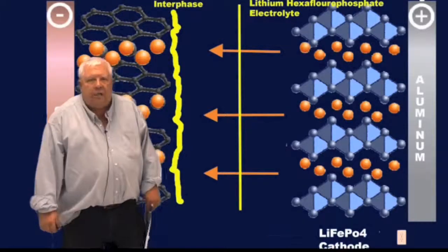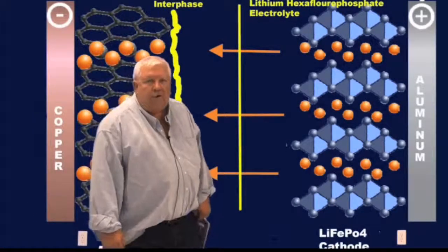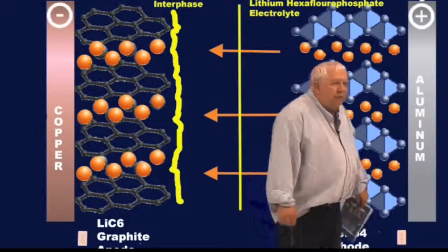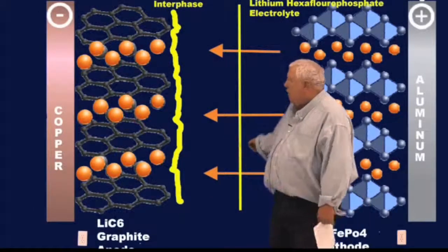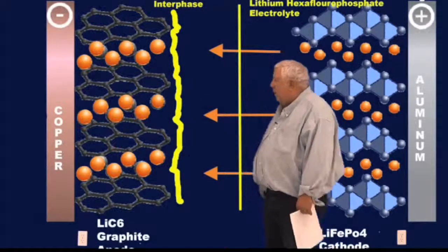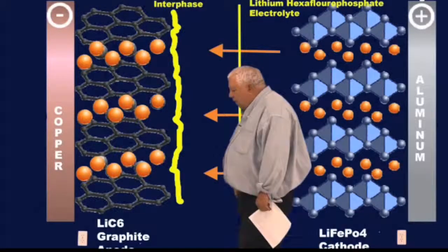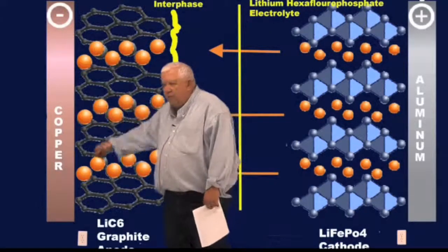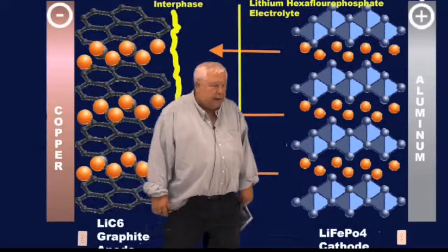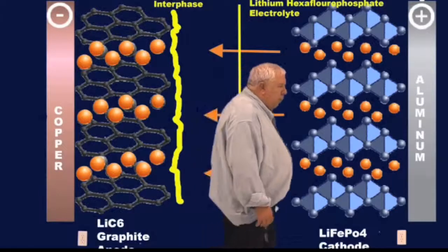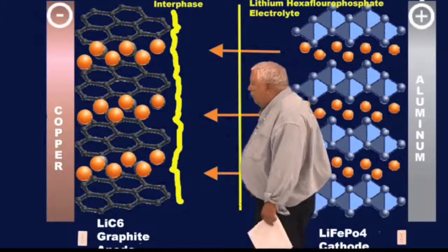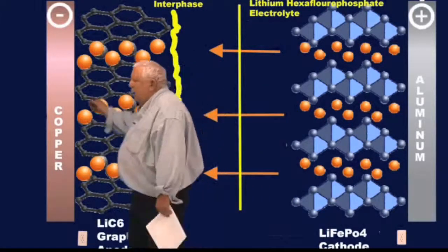allowing all our lithium ions that we've stored there to suddenly begin to react with the solvents in our electrolyte, not in an orderly fashion, as in charging, and not in an orderly fashion such as discharging, but suddenly our SEI layer is breaking down and we've got an inrush of solvents into the intercalated lithium, and that goes into thermal runaway. And so normally a thermal runaway situation starts in the anode, not the cathode.